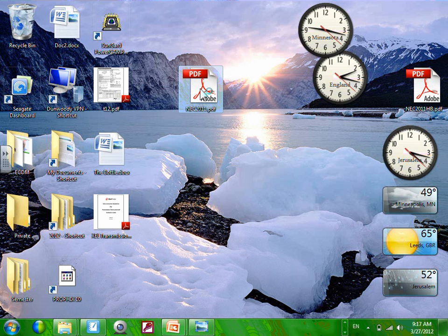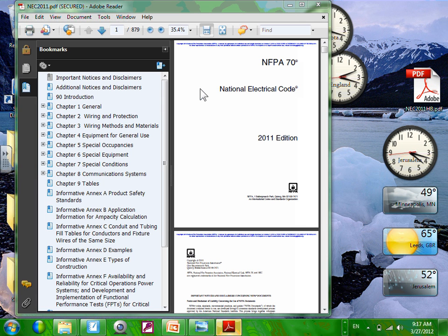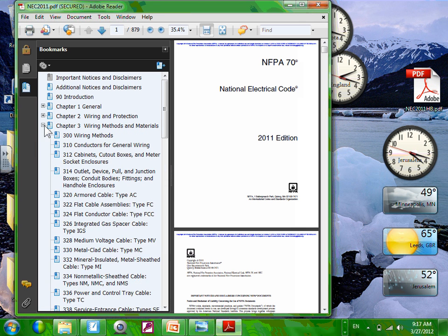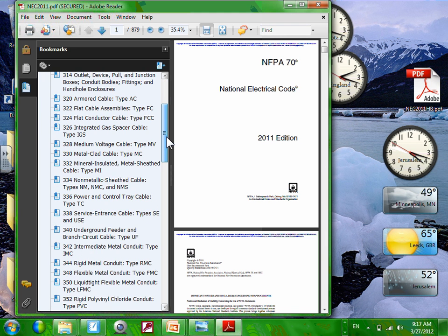Okay, if you guys are at 368, the first thing it will tell you, this is page 225 in the NEC code book, is the scope. You can use it as service entrance, feeders, and branch circuit. Very, very important wiring methods. There are 3 different circuits very dear to your heart and mind in the code. One is service, feeder, and branch circuit. Can I use this as a feeder or a branch circuit? Yeah, bring it on. So look at where it's located under wiring methods, Article 368.